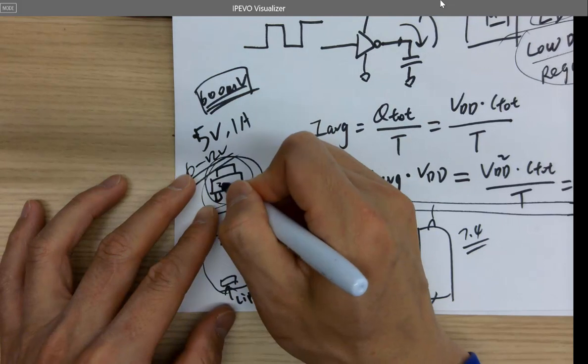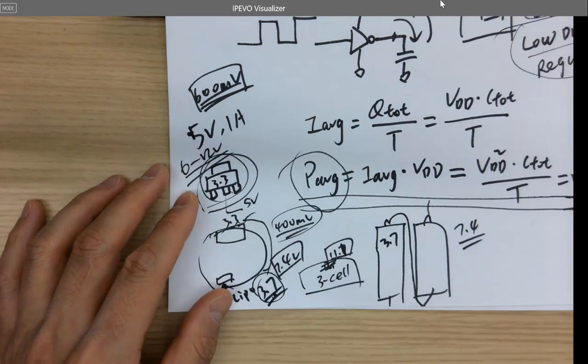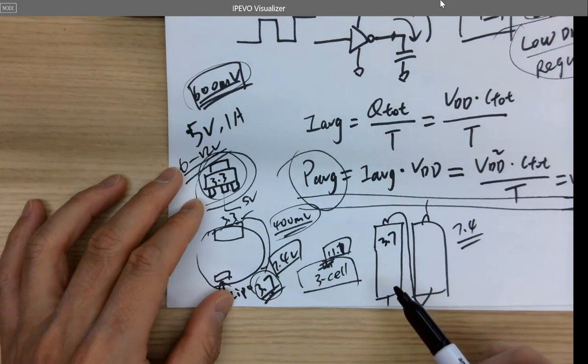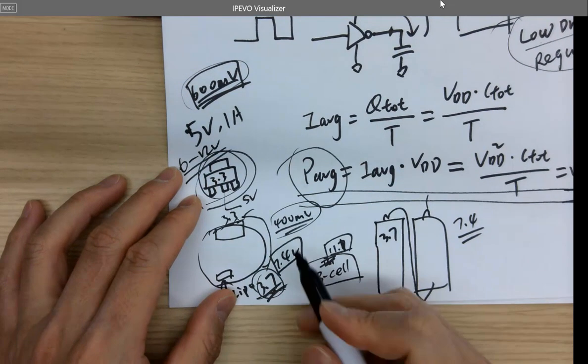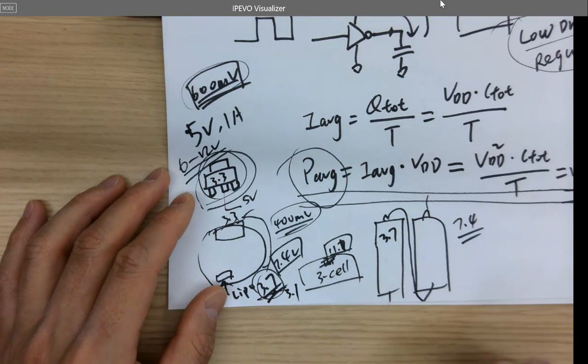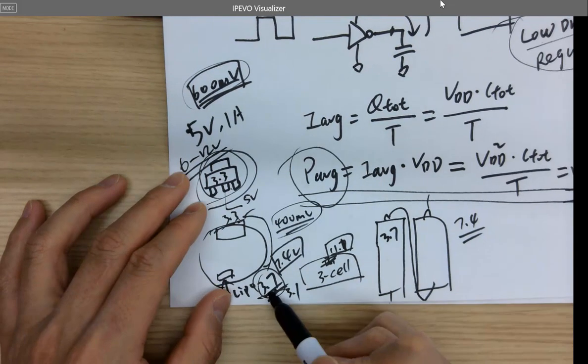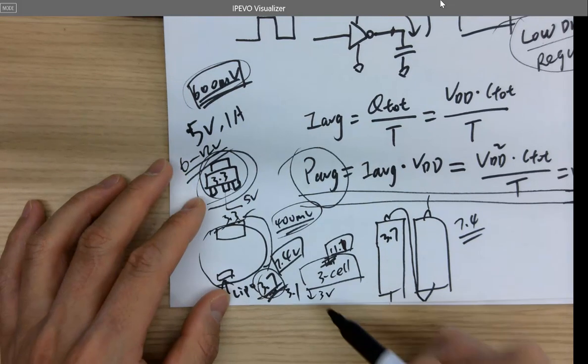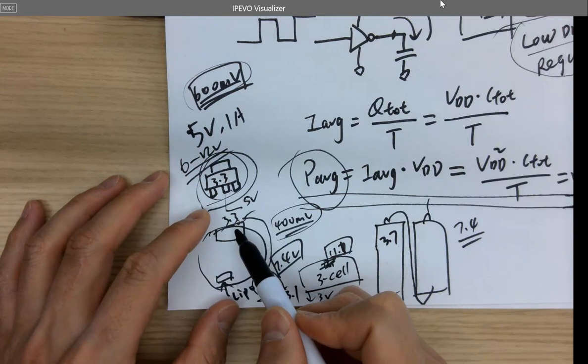You can find a 3.3 volts regulator, the 10-cent version, right? The cheap one. But it's dropping 600 millivolts. So this one, if you drop 600 millivolts, in theory, you're only getting 3.1 volts. If you're losing some of the voltage from the battery, it's getting lower, so it's going to be below 3 volts. You're getting issues powering up.